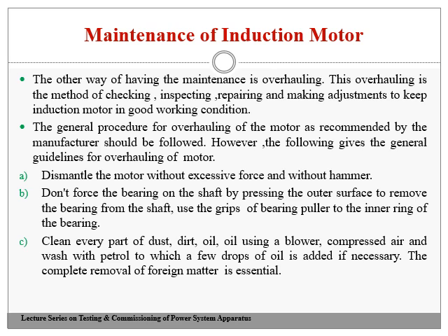That is, all the parts are thoroughly cleaned of dust particles, oil particles or any other fibrous content, by properly using blowers or any solvent that can remove every dust particle on each and every part, so that all the foreign materials accumulated on the inside parts of an induction motor are removed.